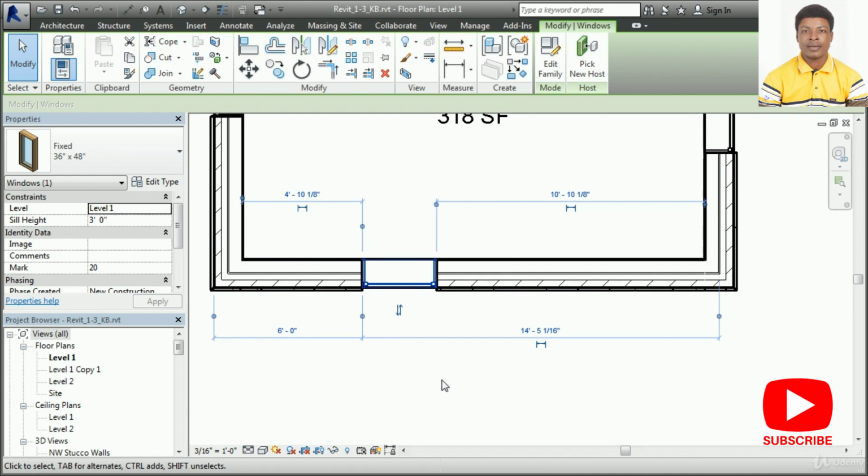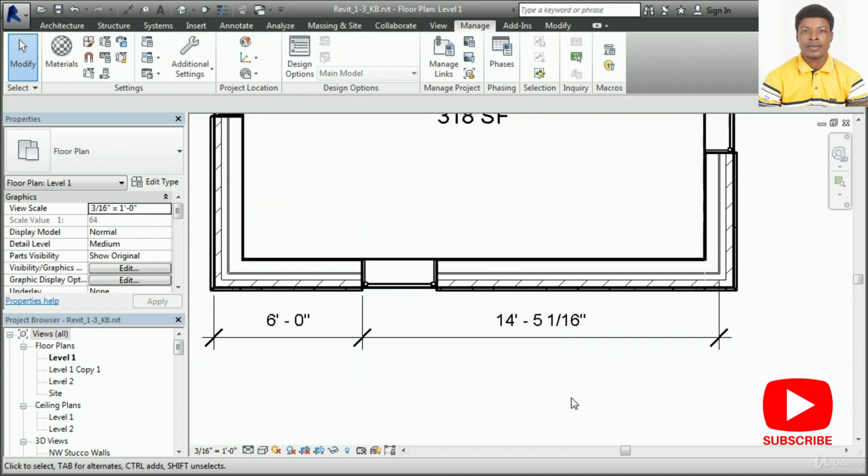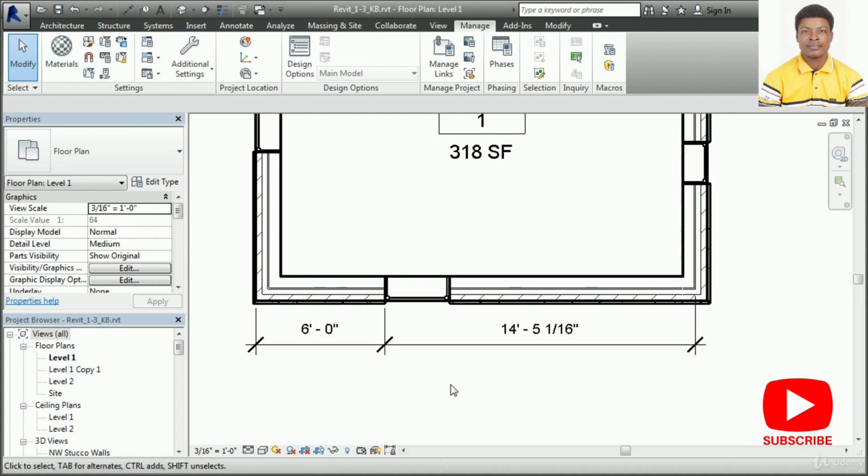When a temporary dimension appears, you can convert it to a permanent dimension by selecting the little dimension symbol below the dimension. Here we're going to be able to create an individual dimension with either of these symbols, and here we'll create a set of dimensions. And if I pick this little blue symbol, we've just created a permanent dimension.